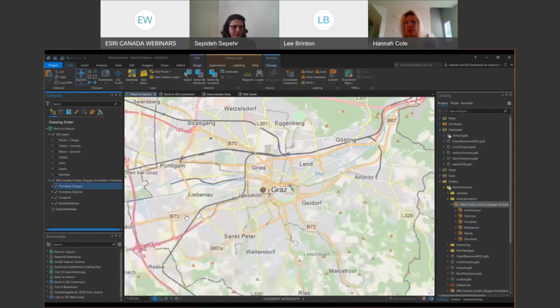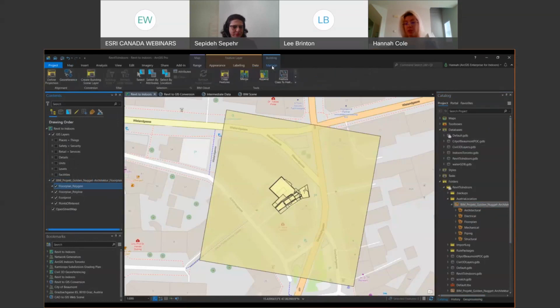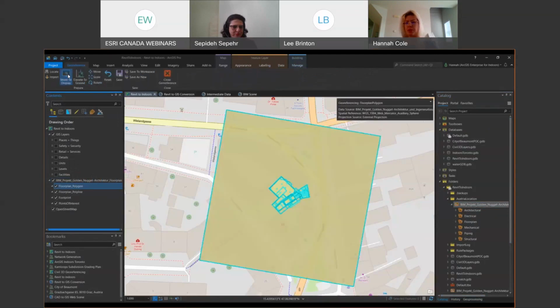ArcGIS Pro's georeferencing toolbar is used with Revit data in a very similar way as when georeferencing a Civil 3D or a CAD file in ArcGIS Pro. Georeferencing is required for your Revit data before it can be mapped in a 3D scene in ArcGIS at any time. These 3D scenes can reside either in ArcGIS Pro or in any web client you wish to consume your data with.